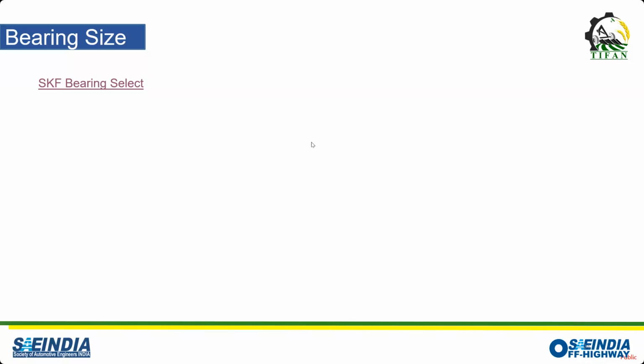So this is just for example, right? You can check your own. There are different suppliers apart from SKF. So you can just go there and put these values. Mostly it will ask you the inner diameter, outer diameter, width, and then load ratings. If you provide all these four data, then they will recommend the bearings which you can use in your systems. Then you can use that one directly.